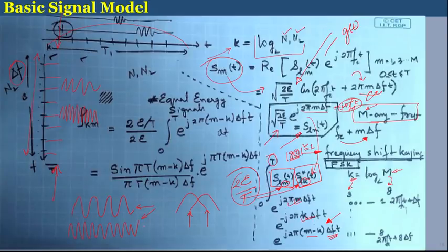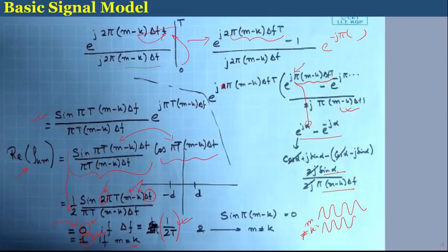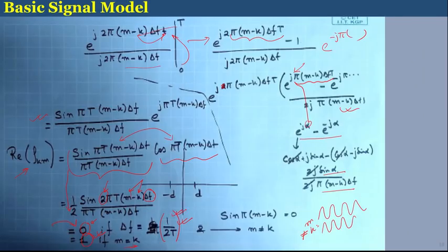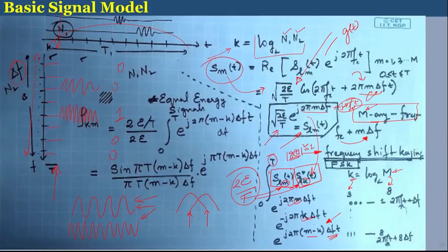Whereas, if the signals are matched to each other, the same signal, then you are going to get a 1, indicating that only one of these will give a value of 1 at the end of the matched filtering operation, and others are going to give a 0, by virtue of the orthogonality condition. So, if we set delta f equal to 1 by T, which is by the orthogonality condition, although the spectrum will overlap, still we will be able to distinguish between the different frequencies by virtue of the orthogonality criteria.